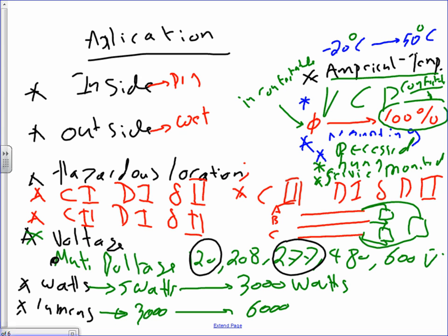Okay, so lumens. Now, we talked about the voltage, we'll talk about the lumens. What the heck is a lumens? When they manufacture that fixture right above your head, when they start the arc and they treat the arc with the phosphorus material inside, the manufacturer tests these to get you how many lumens, the unit of light is lumens, how many lumens this arc with the phosphorus, with the type of tube that you're using, is it T5 or T8 or T12, they test them and give them a value called the lumen value.